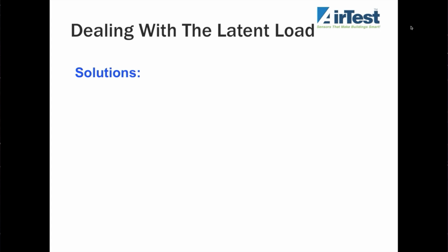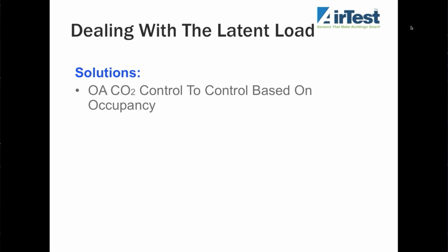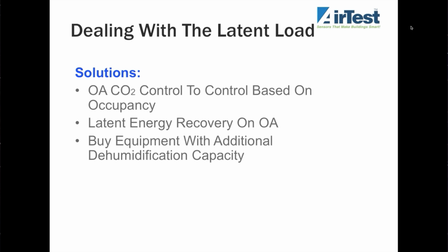And in dealing with that moisture problem, if we can measure it properly, there are plenty of ways that we can deal with it. And that includes, one thing we've just talked about, using CO2 control to control the amount of outside air that comes in, which is a major source of moisture, so that we're only bringing in as much air as we need for the occupancy in the space. There's also the possibility of putting latent recovery on outside air intakes, which include energy wheels or enthalpy wheels. You can actually buy equipment.